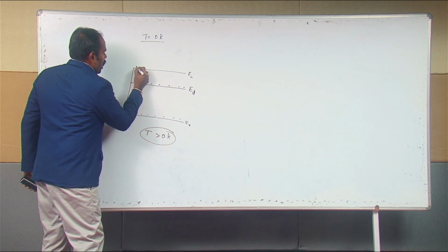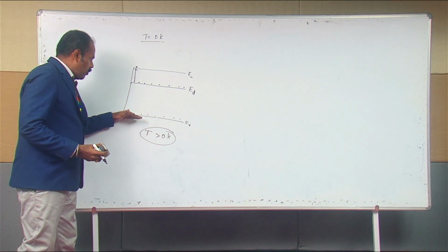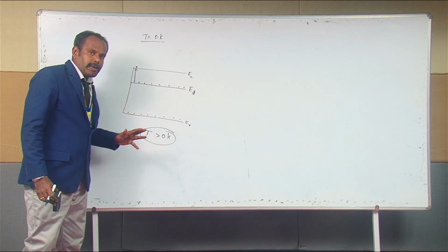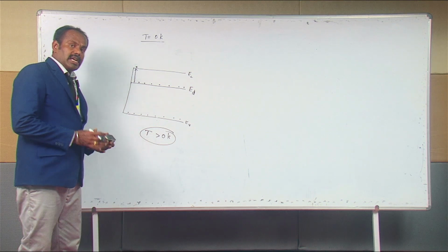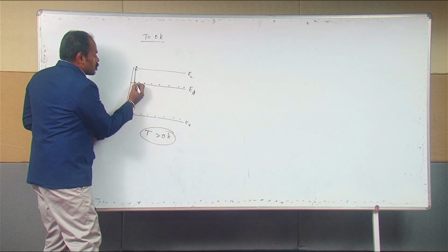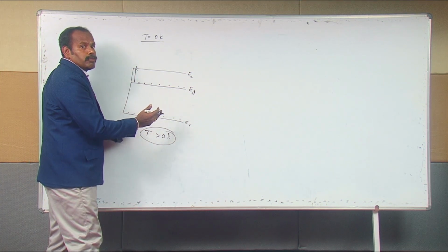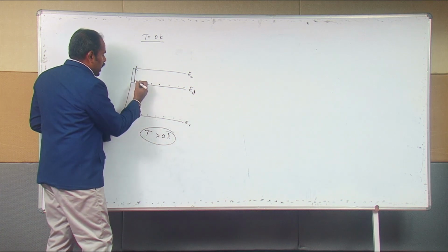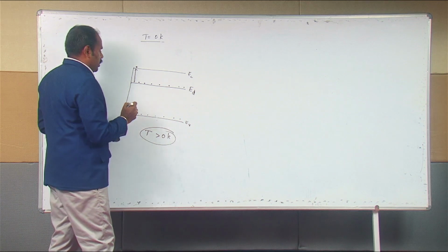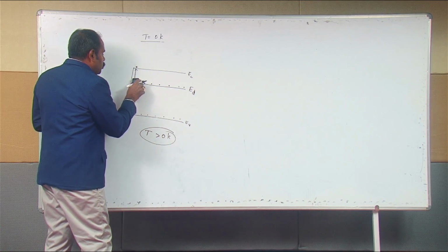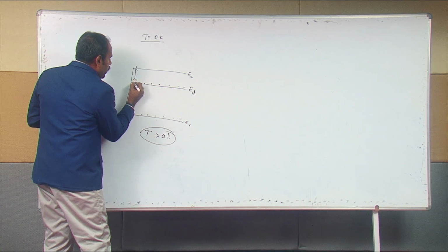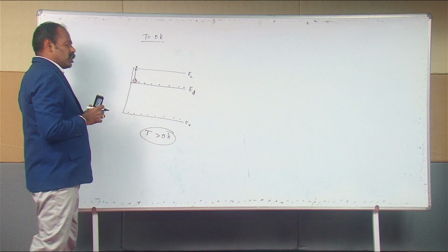Okay. Instead of the electron moving from the valence band to the conduction band, as in the case of an intrinsic semiconductor, what is happening now? Once you start to increase the temperature, initially the free electrons introduced by the pentavalent impurity atom, which are residing at the donor energy level, will first gain energy and make the transition to the conduction band. And once an electron moves to the conduction band from the donor energy level ED, correspondingly a positively ionized donor atom is introduced in the donor energy level.